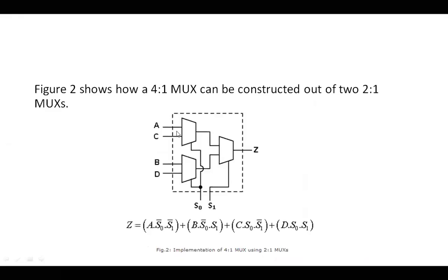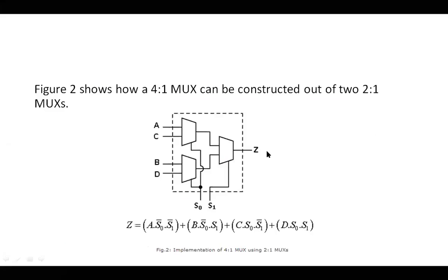We have seen this in our initial classes, as to how I use 2:1 MUX, combine them and give them to another output here, which is Z. So my A, B, C, D is here, and then I have my select lines S0. S0 is common to both the first MUX and second MUX, and then S1. When S1 is high, it's going to take outputs from stage 1. So this is my stage 1. This is my stage 2 MUX. So when S is high, these are enabled.